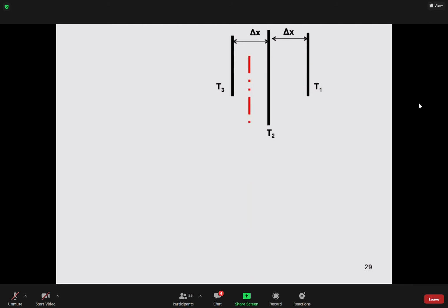Therefore, we divide the surface area between these two, okay? Here is node number 1, T1, and here T2. And the distance between them is delta X. Therefore, we draw a boundary here, and we mention this is the boundary between node number 1 and node number 2. So this half belongs to here and half belongs to here. Again, the distance between T2 and T3 is delta X. I divided equally, so this part belongs to T2 and this part belongs to T3.